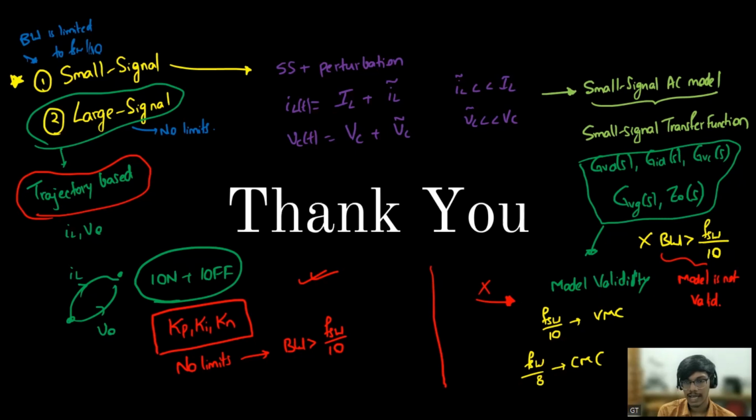Say before we take a sample, the disturbance is gone, then our ADC will not capture that disturbance, and neither the small signal nor the large signal will capture it. But if the ADC captures it in both cases, how fast does the converter react to that disturbance and come back to its initial condition? That defines the bandwidth, you can say, or the speed, because the ADC has to capture the data, right? We are using the same hardware, everything, only the gains are different.